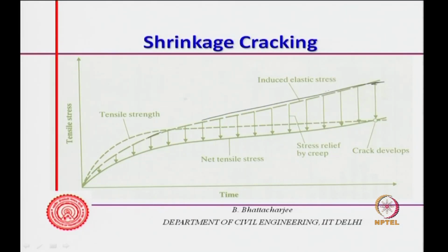This might be the induced tensile stress because of the restraint, and this will change with time, because shrinkage will increase with time, therefore stress will increase with time, right. And this is the tensile strength. In the beginning the induced stress could be less than the tensile strength, but if it crosses the tensile strength, cracking would come.